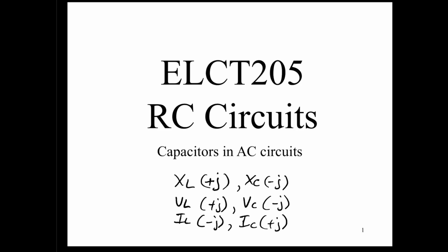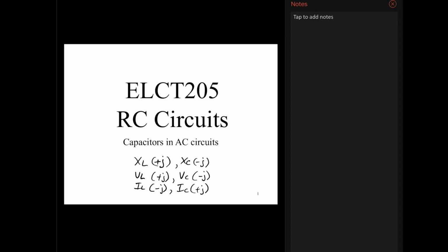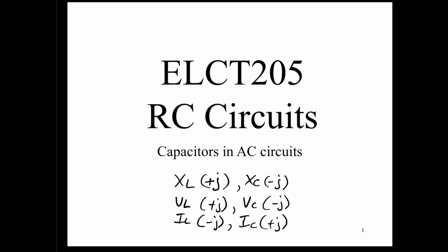Remember, we had that acronym that helped us remember the voltage current relationship for inductors as ELI, which indicated the current will lag the voltage by 90 degrees for a pure inductor. When it comes to capacitance, we have ICE. And what does that mean? That means that if voltage is still the reference, then we have current leading the voltage by 90 degrees for a pure capacitor, and we'll see that as we take a look at this presentation. So I just wanted to start with that.